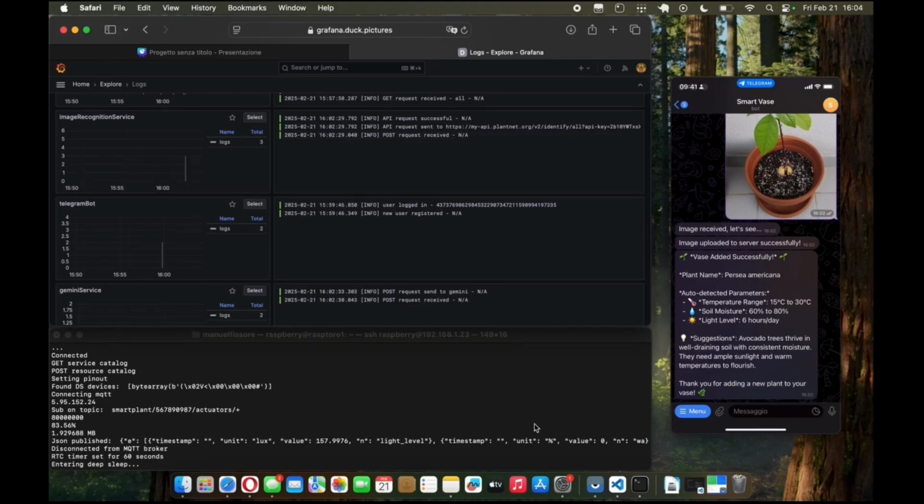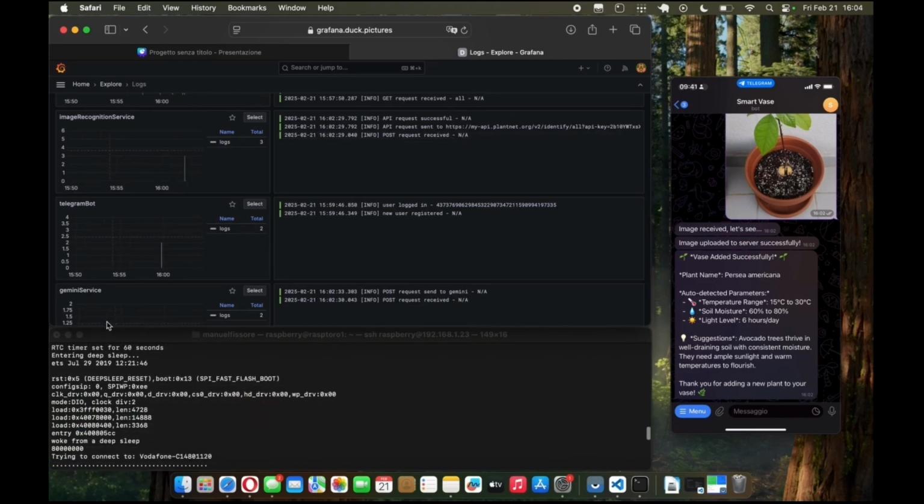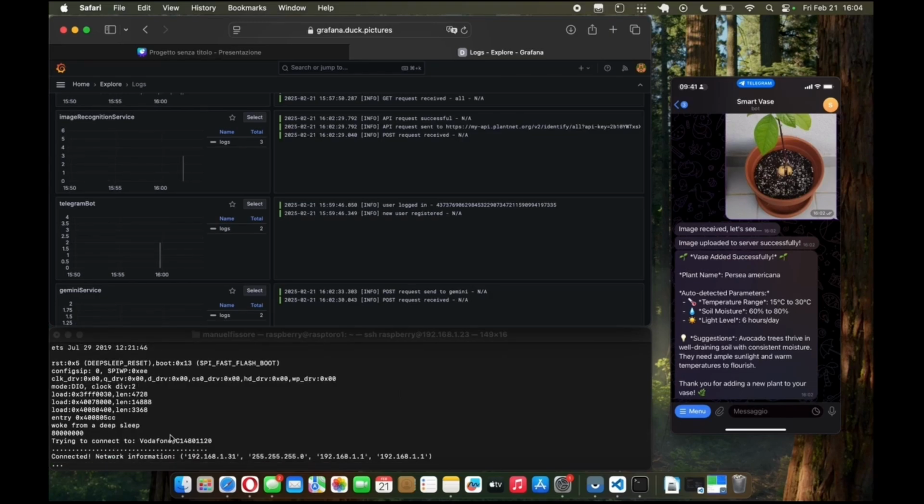The device uses an intermittent computing paradigm, basically going to sleep for a fixed period of time and then waking to send and receive data. This is allowed by the MQTT event-driven async nature. Once awake, the device will set the clock frequency to the lowest possible in order to save energy and try to connect to a saved Wi-Fi configuration.